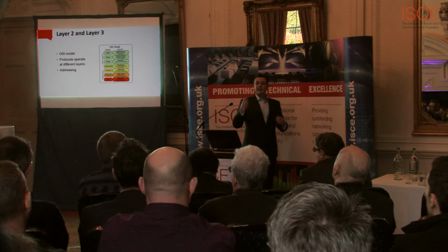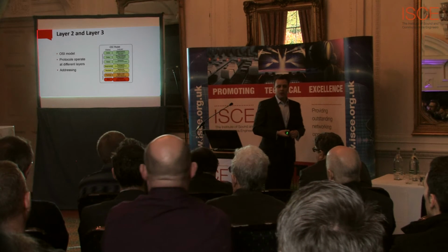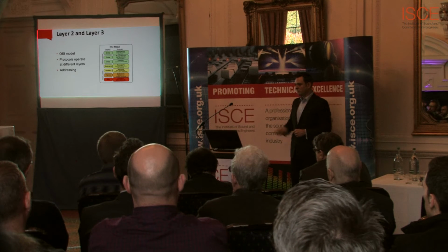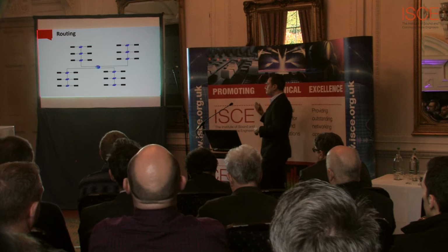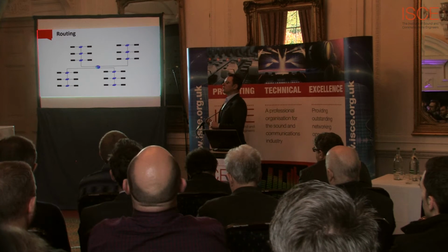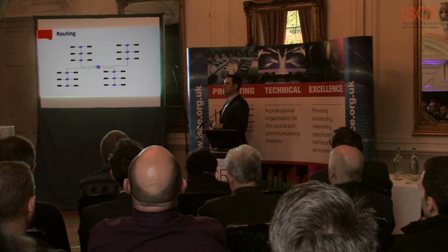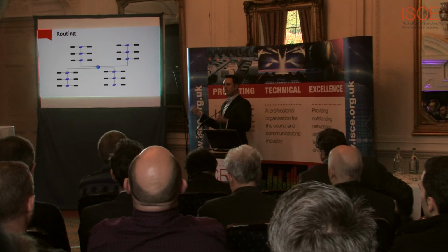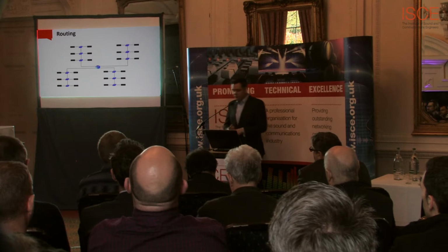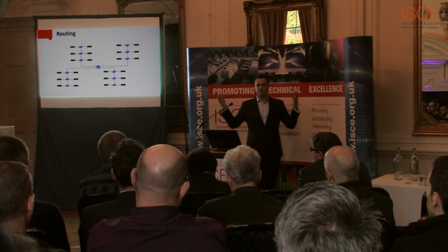What logical addressing allows, in theory, is to do routing. And that's where most of the miscommunication and misassumptions occur, because people will immediately associate layer 3 with routable. And it seems that in the world of network audio, being able to route is the holy grail.